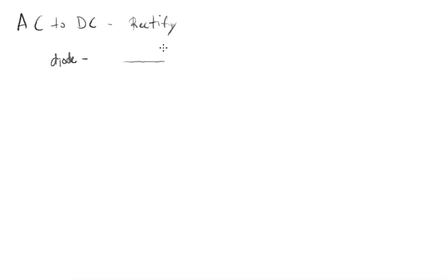But basically, we have an electrical symbol for it. It looks like this. It's like an arrow with a line on the front of it. And the interesting thing about these diodes is they allow current to go in one direction. So current could flow this direction, right? But current could not flow in this direction. So not in that direction, but yes, it can flow in that direction. And so this is our key to rectifying current. And in fact, a single diode like this is what is called a half wave rectifier.